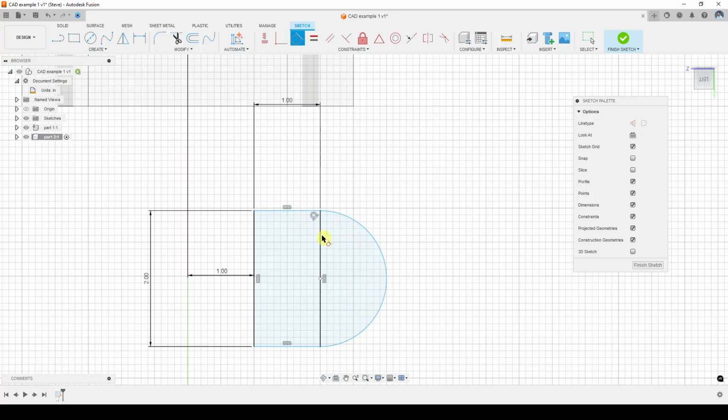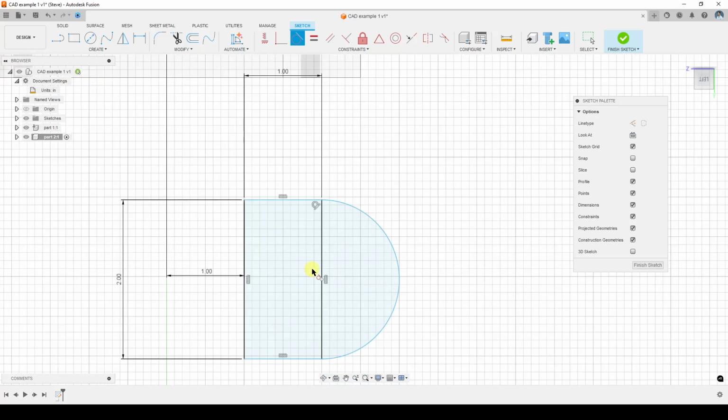And it would be back there again, and I get that tangency constraint up there. Okay, so now I want to revolve essentially this geometry around the center, but I have this line in the middle. You can leave that there and just select 2 geometries and then make them concentric, but you can also trim geometry from your overall geometry if you don't want it.